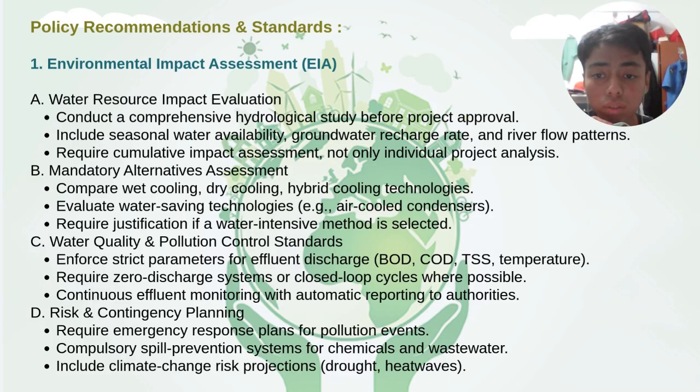Policy recommendation and standard. First, environmental impact assessment (EIA). A, water resource impact evaluation: conduct a comprehensive hydrological study before project approval, and include the water availability, water recharge rate, and river flow pattern. Require cumulative impact assessment, not only single project analysis. B, mandatory alternative assessment: compare wet cooling, dry cooling, and hybrid cooling technologies. Evaluate water saving technologies, for example air-cooled condensers, and require justification if a water intensive method is selected.